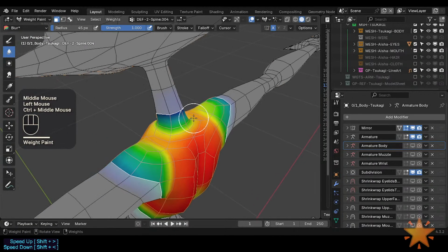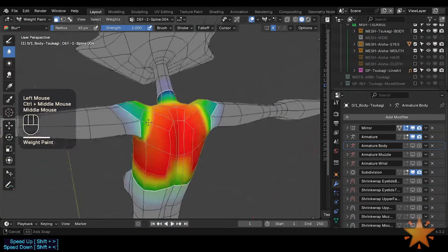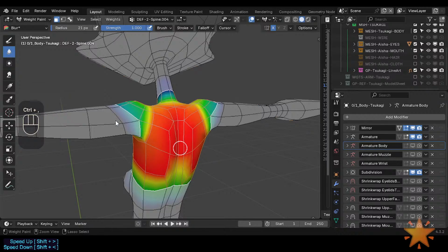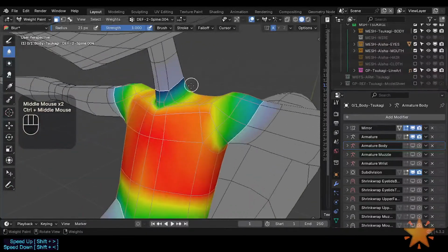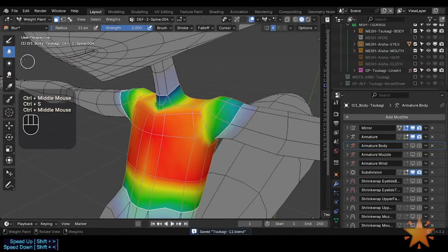And just another tip, particularly in this Blender version, but probably before, there is this extension now, which is Easy Weights. So you get Easy Weights, and I have here the always auto clean option. What that means is super useful, because if we have this on, we can combine it with this mix thing to have it work as if it was a subtract. I'll show a clear example here, but I'm gonna save before.